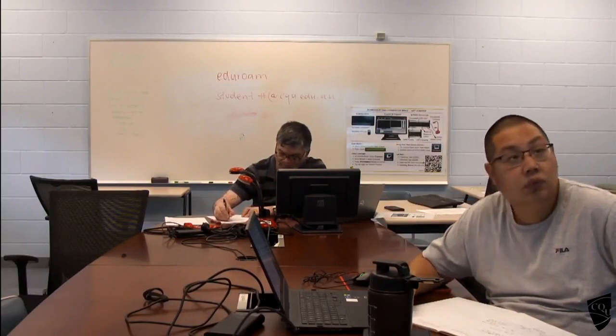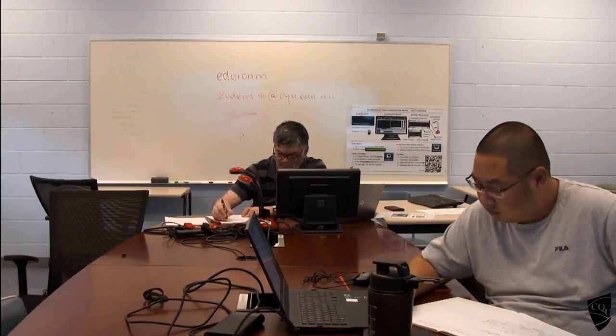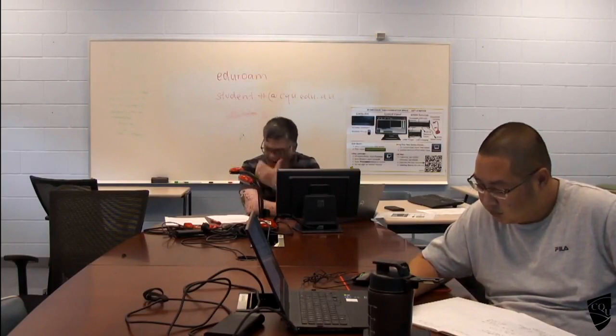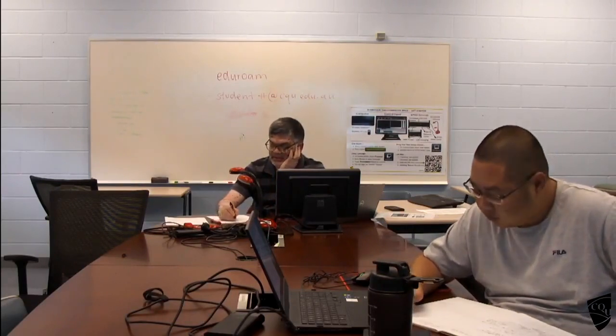I value is bd cubed upon 12. So about the centroidal axis, the I value for a rectangular section is bd cubed upon 12. B is generally parallel to the axis, and d is perpendicular to the axis.